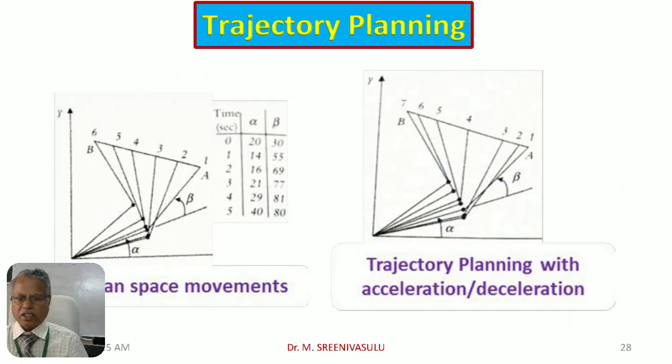And in the other two sketches, the first one is actually trying to give you a normalized one, whereas we will not be able to implement that in the program. The major reason is that if you want uniform variations with respect to velocity, then at the starting and end points also, acceleration should be more. So pickup should be more and deceleration also should be more at the end, which is not possible. That's why slow pickup in the beginning and slowly stopping in the end, meaning deceleration in the end, should be adopted. By adopting them, once again, the total motion was regulated.